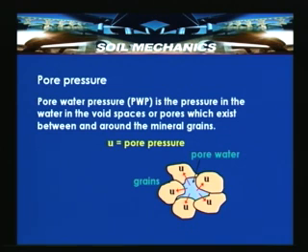So, an illustration is shown here. u is the pore water pressure designated here, and these are the individual grains with a certain arrangement. If you assume that the entire pore space is filled with water, that water is called the pore water. When it is under pressure, the pressure exerted onto the internal boundaries of the grains in this particular pore space is called the pore water pressure, and this can act in any direction because of Pascal's law.